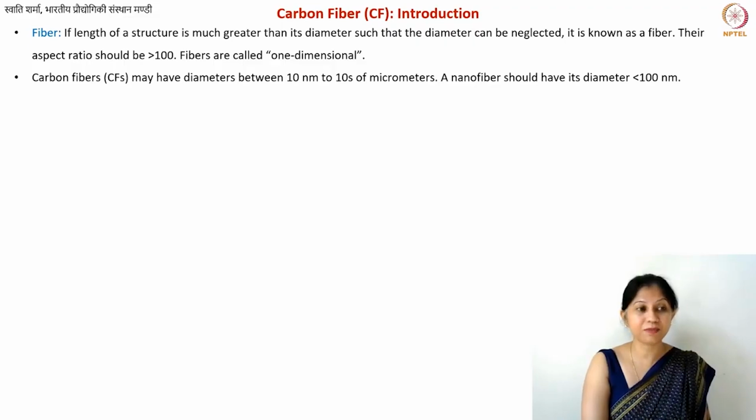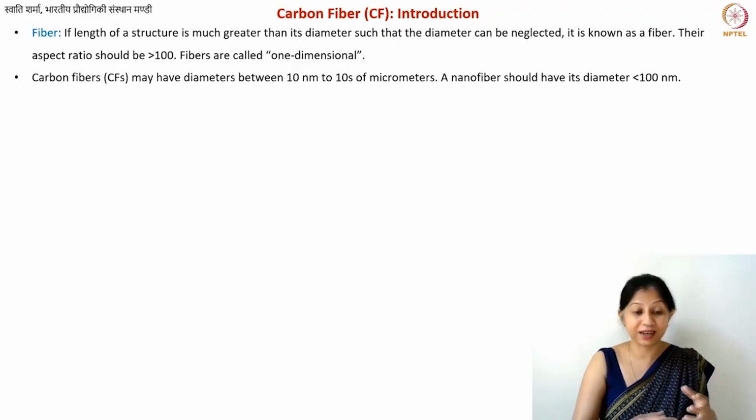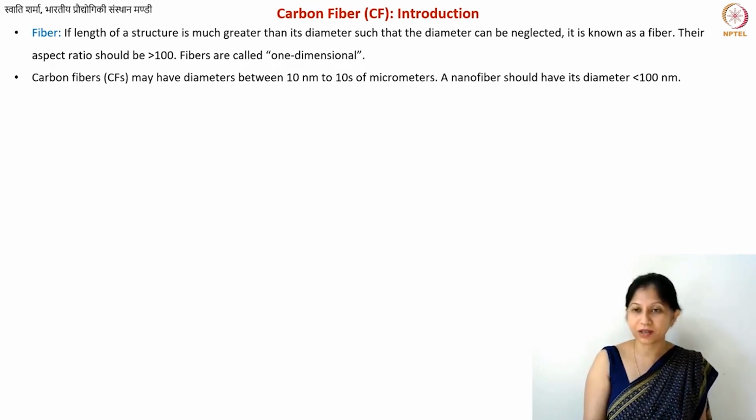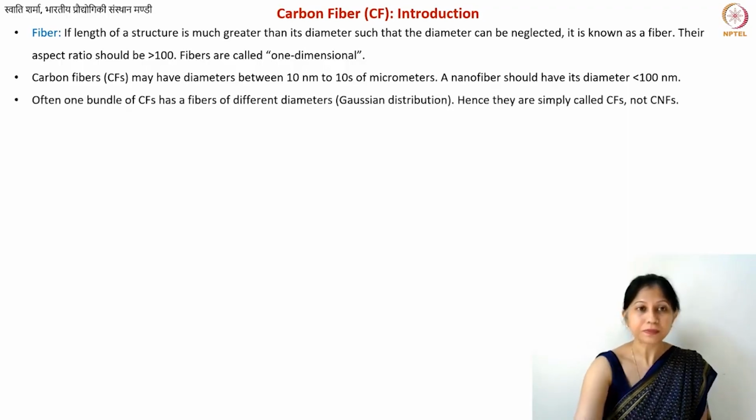So even certain polymers, which if you make large scale structures from them, those structures might be non-graphitizing, but in the case of carbon fibers, it is easier for the defects to anneal out, and that is why there is always a possibility that you can get graphite out of polymers where you don't expect that. If you make other structures from those polymers, then you may not get the graphitizing carbon. And that is why the safest terminology is carbon fiber.